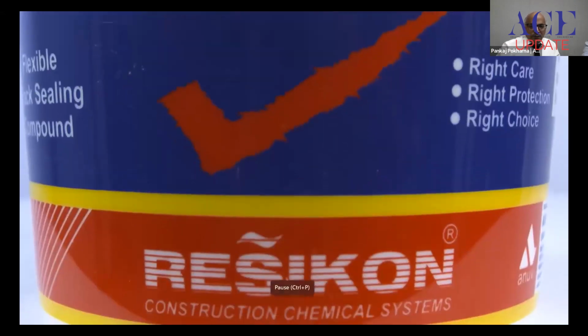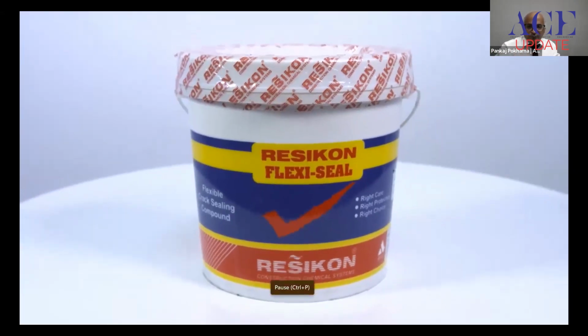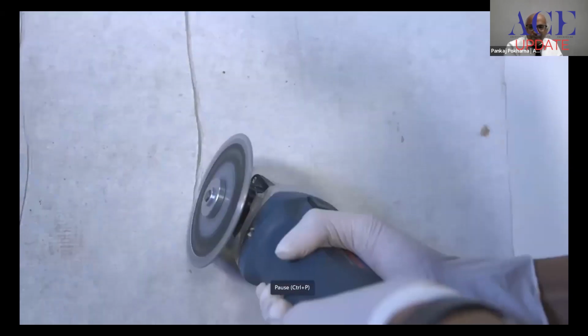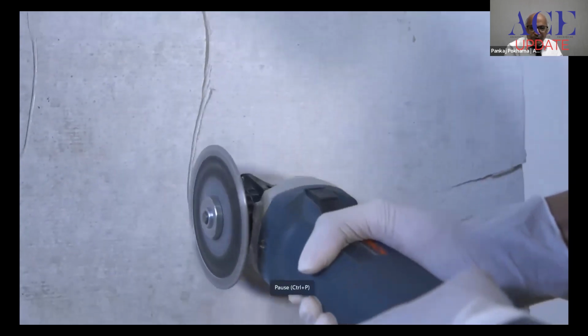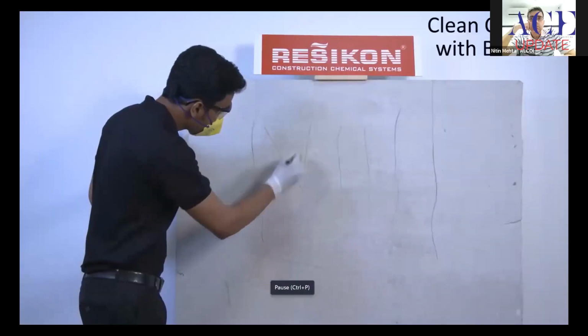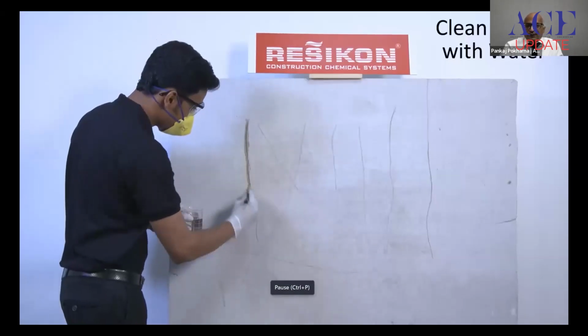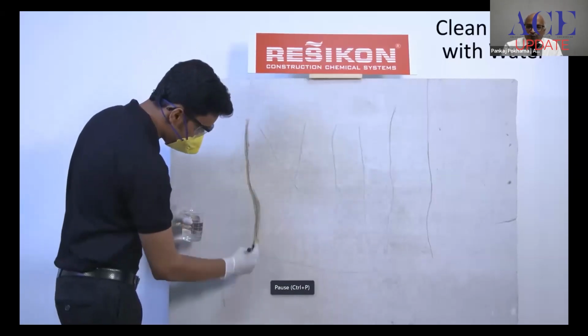So you can see the application which we are doing on the cracks. When you find cracks like this, you have to cut open them properly with the grinder, which is shown here, and then clean it with a brush. Also, you have to wash it with water. So now this application is showing the water application.